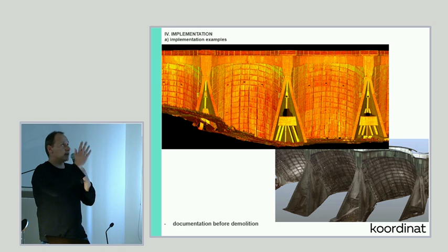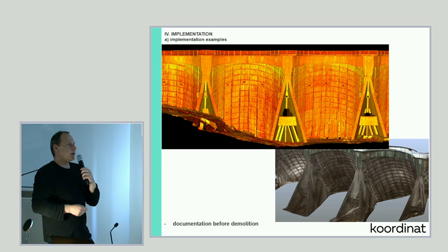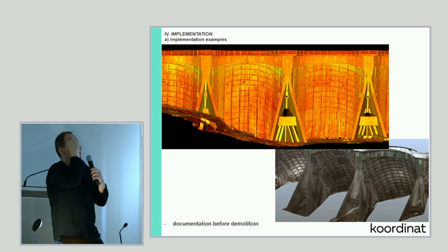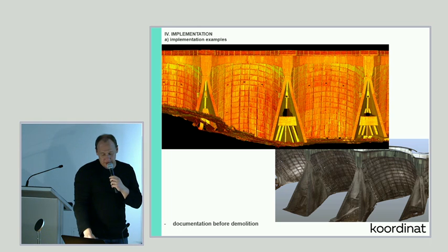So I used both types of scanners. The phase one to have coverage of the insides of the arc and interiors of the pillars, and the pulse base to have the top from a little bit further distance.